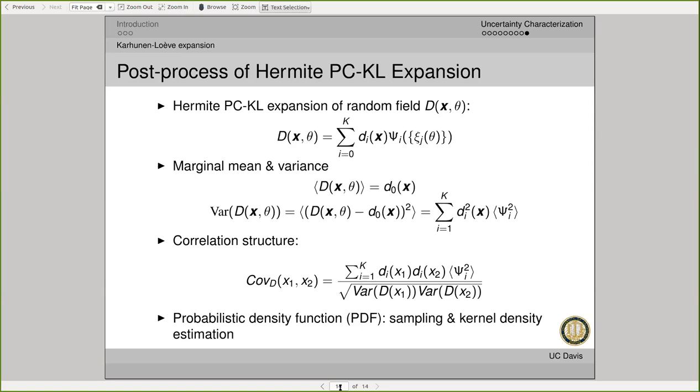So we have now explained essentially the way to approach this problem: to expand into probability spaces using polynomial chaos, and to take into account the uncertain random field of the material, all the coefficients, and also to take into account the uncertain process, the earthquake in this case, as loads. We use the domain reduction method, so that's how we convert earthquake motions into loads. I guess the next step will be to start talking about stochastic elastic-plastic finite elements, but that's going to come next.